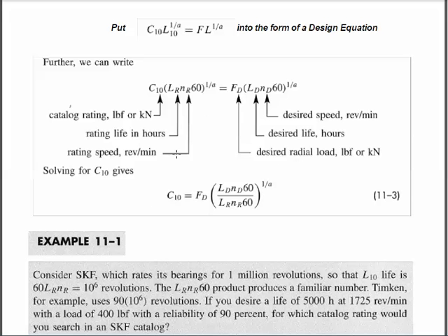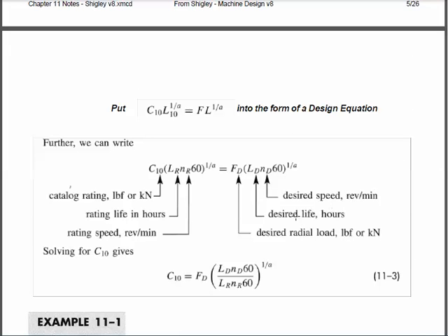Okay, and so one of the things that this equation might be used for is selecting a bearing. So let's think about this. I plan to use a bearing and apply a known load to it. I've done the statics on the shaft and I know what force I'm going to pass through that bearing. I know exactly how many hours I need this thing to run at a certain RPM. Okay, I know that information. That's my design goal for this bearing. So I know the load, I know the life, I know the constant over here. So in fact, what I have on this side is an entirely known thing, or the constant.